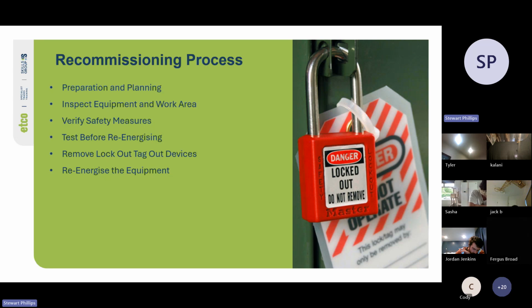You'll also do the same when you're turning on the motor control circuits. You'll test that if you put it in forwards, you can't then put it in reverse at the same time. And if you put it in reverse, you can't put it into start at the same time. If you've got star delta starters, which is something you guys will learn about later on, where it energizes the circuit in one configuration and then after 10, 20 seconds changes over, we need to make sure that we're starting the process, waiting for the correct timing, and then watching it click over and making sure the correct contactor is engaged at the right time.